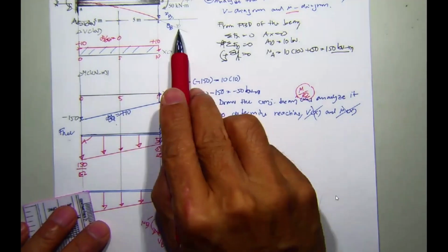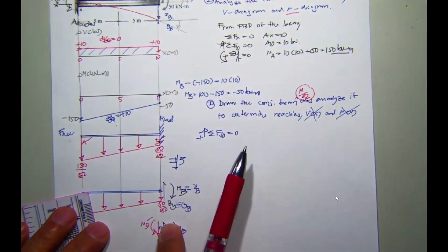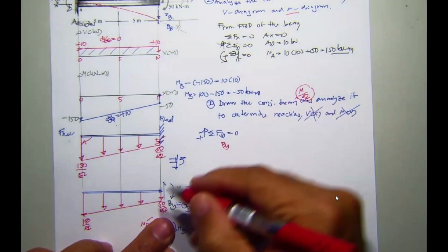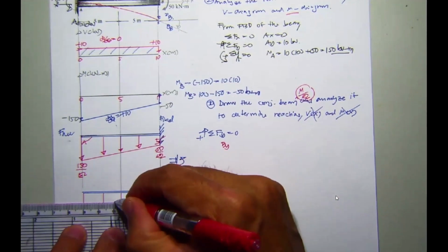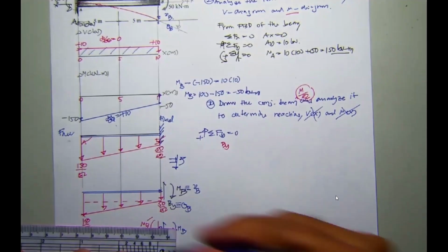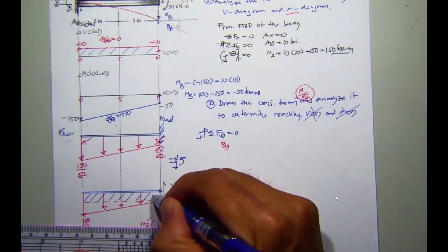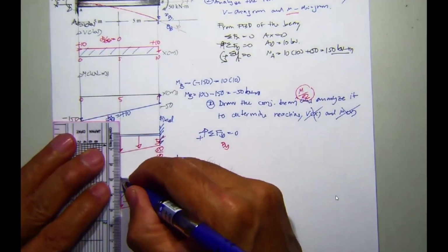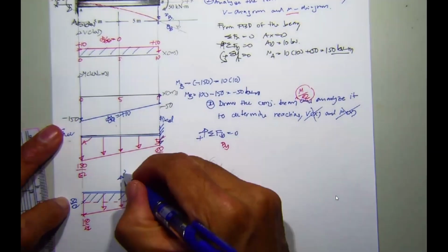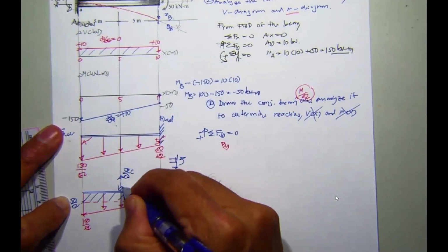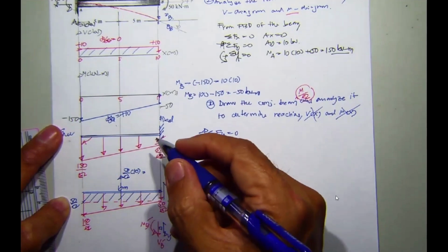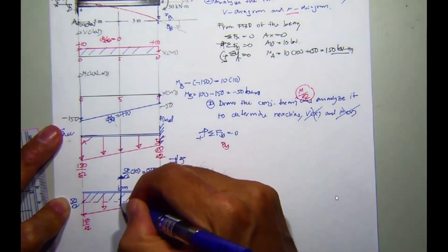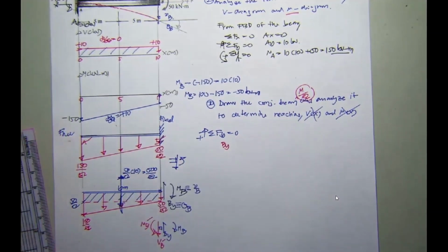And then we will get the direction for the elastic curve. Don't get involved with this sign convention, you'll mess up. Now, following this one, B sub Y upward. This one separates into two portions. The first one has the value over here of 50 over EI, and this provides the resultant force of 50 over EI times the length of 10 meters. So this one is 500 over EI. Oh sorry, in this downward direction, not upward.